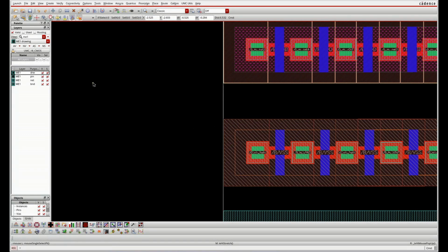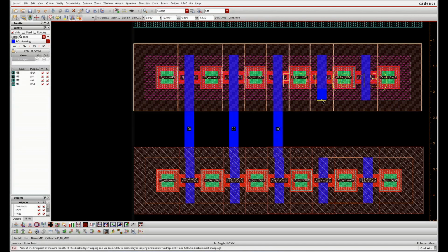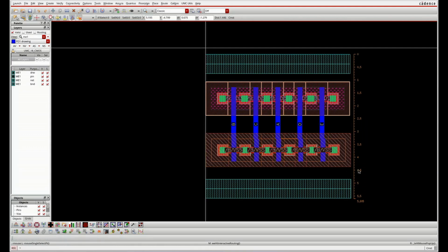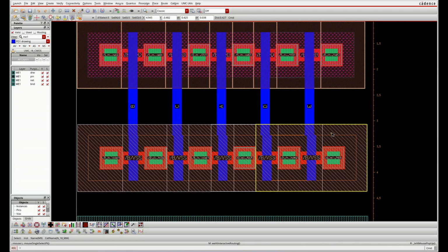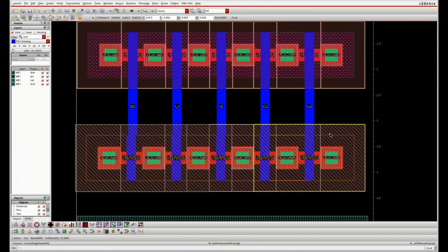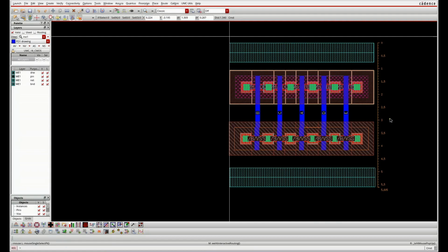Now, as we have aligned our gate to the PMOS through the Euler method, you can see here it is marking BCADE. So you align the PMOS, as it is not properly aligned. So here it is, BCADE alignment. You can see here.